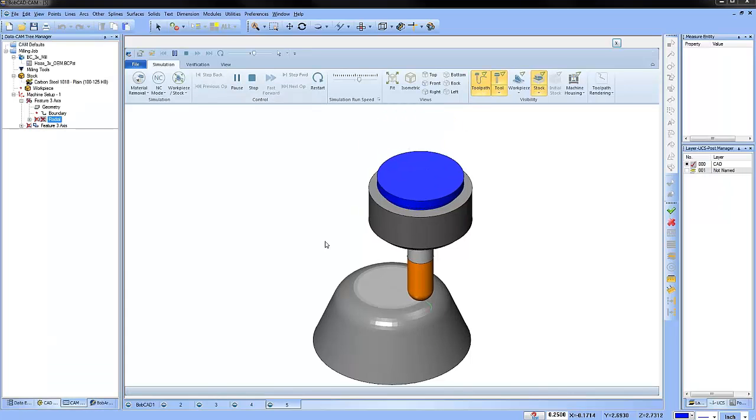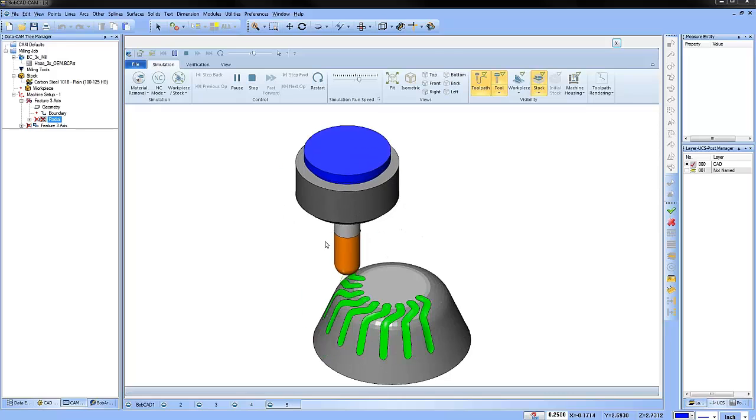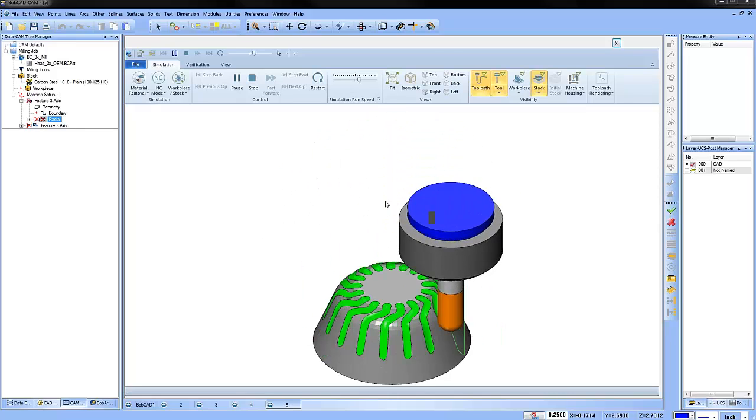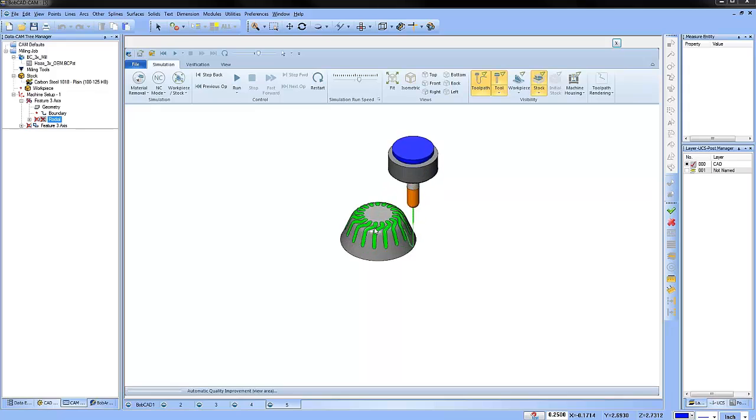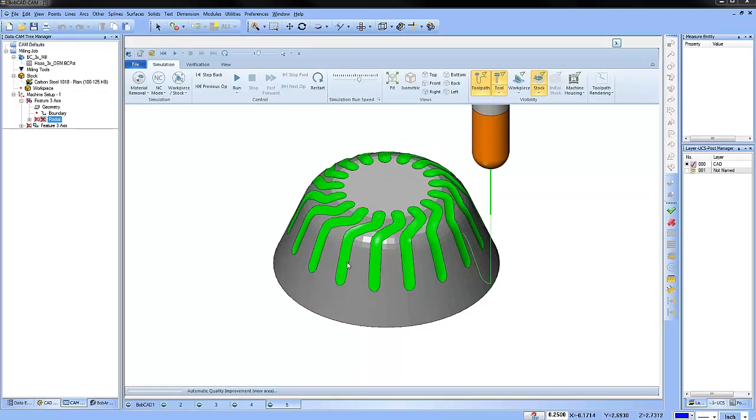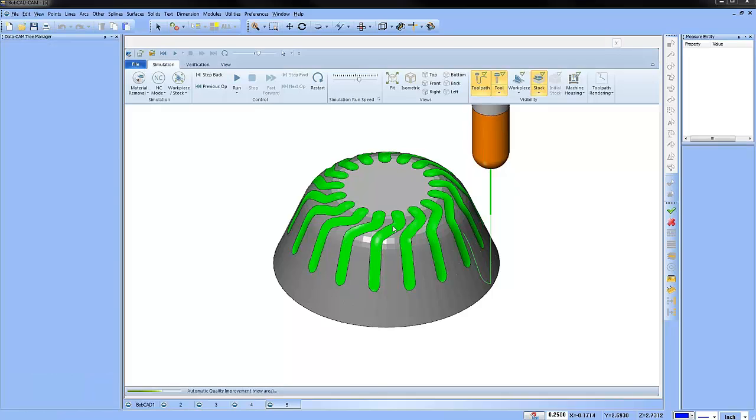Then the next thing I did is I used the project curves, or actually this one showing the project curves 3D toolpath, where I was able to create kind of like a zig pattern in there, which you wouldn't get with the traditional radial type toolpath, because it would just start from the center and work its way out, or go from the outside and work its way in. So using the project toolpath, I was able to use some custom geometry to create a different effect, okay?